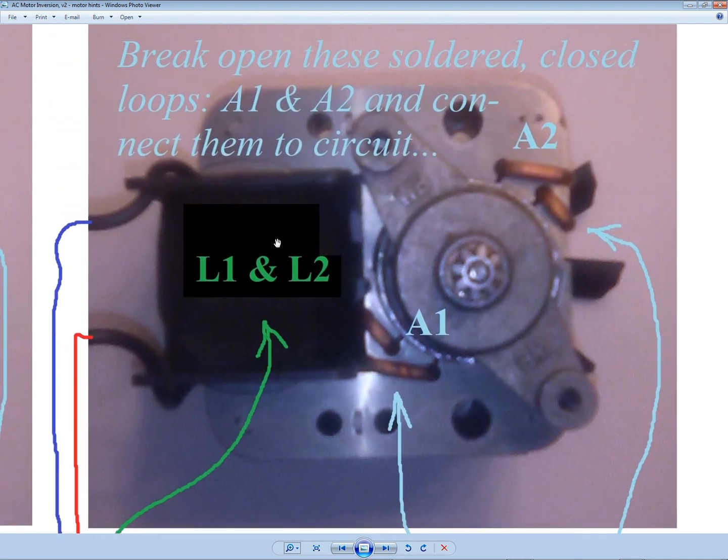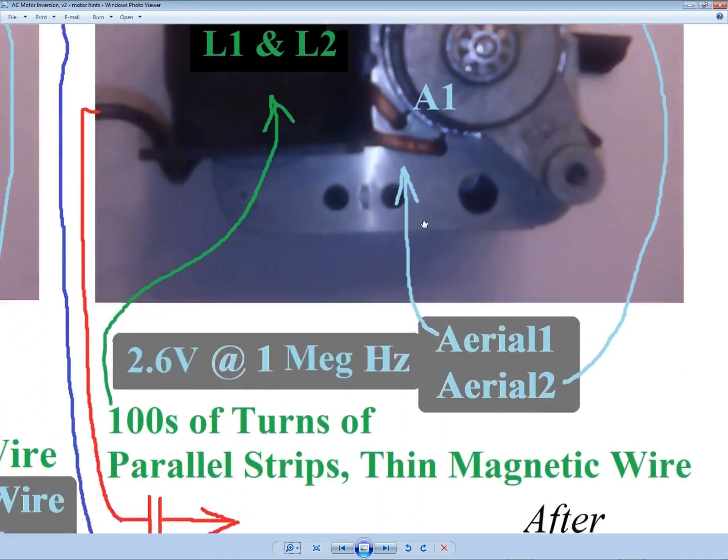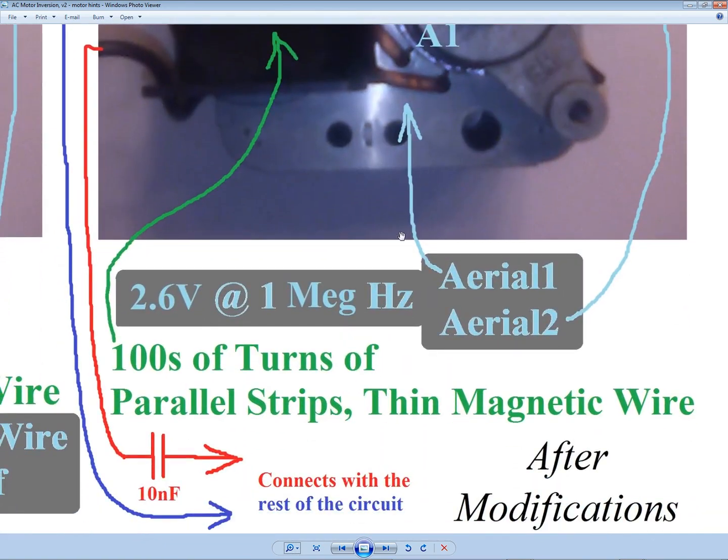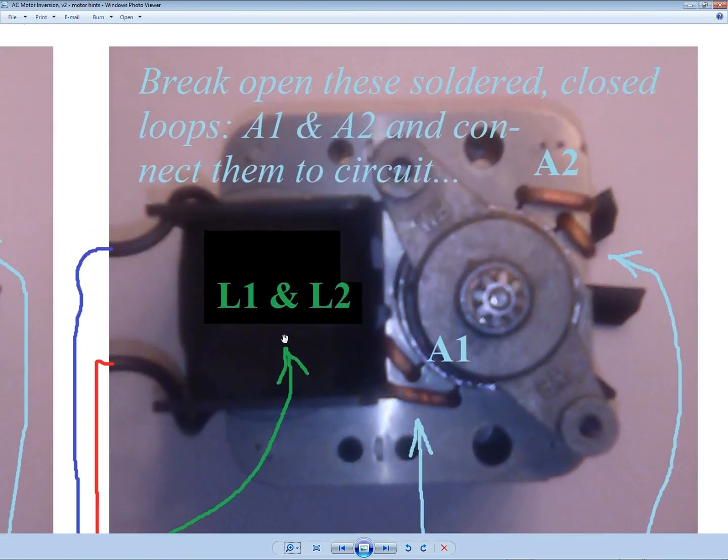But you have to feed them not to the voltage coil, but to the current coils, which are normally called starter coils. And then you have to make this a bifilar winding. You don't have to, but it certainly improves performance. Actually, it detracts from performance if you create any more than a bifilar winding, such as trifilar, quadrifilar, and upwards.